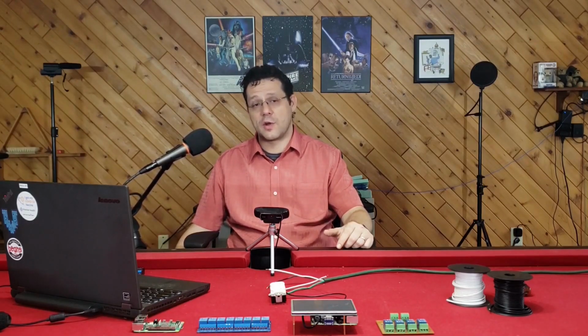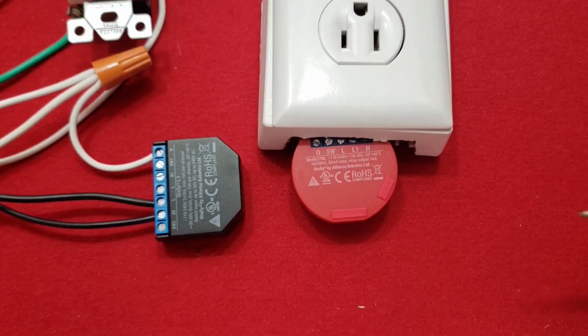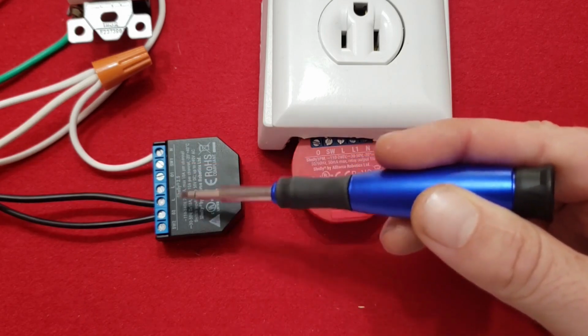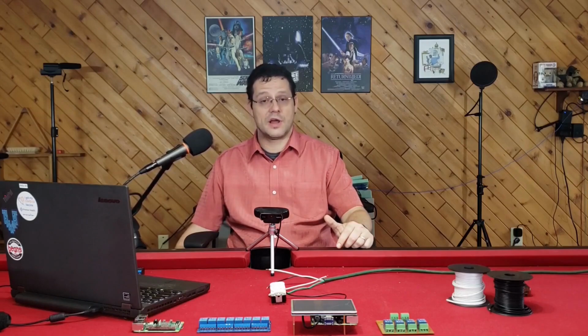There are ways of integrating another relay in order to use these, and that's actually the next video, but it's more complicated and perhaps marginally overkill. We'll see. At any rate, the last connection you need to make is the output, marked as O on the Shelly 1 and O1 and O2 on the 2.5 for the first and second outputs respectively. That's it. The relay is now ready to be powered on and configured.